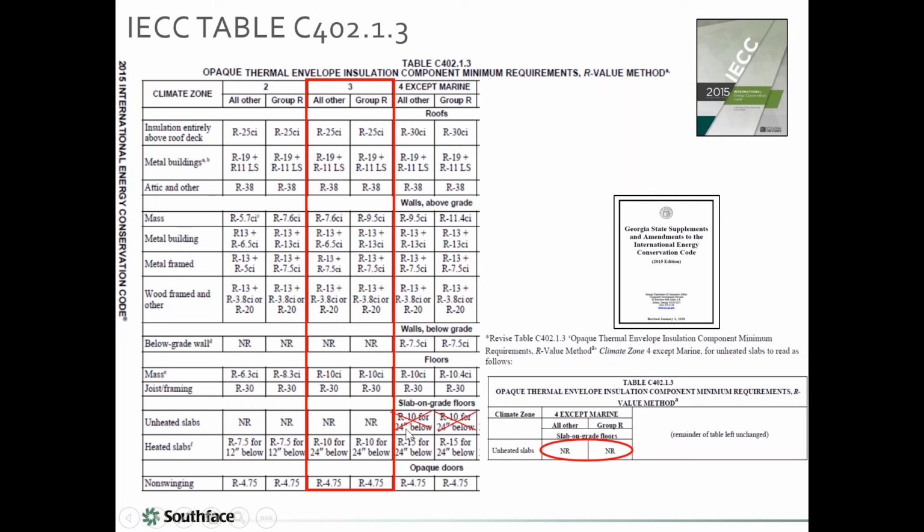No slab insulation. Georgia amended out the requirements for it in zone 4. So if you go to IECC, you don't need slab edge insulation. It's not a big deal to trade that off. It's not a huge impact. Mostly it's about air conditioning buildings in the South.